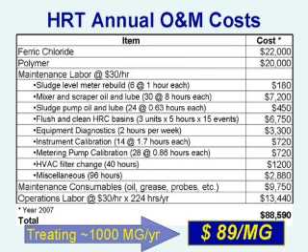The cost of construction for this facility, which was primarily constructed between 2006 and 2007, was $67 million, and that included not only the ballasted flocculation facility, but also the ancillary facilities that were required for the project, including screening and pump station modifications, grit removal, and the effluent channel and chemical storage and feed. Total of $67 million for the project, which effectively works out to about 29 cents per gallon per day.